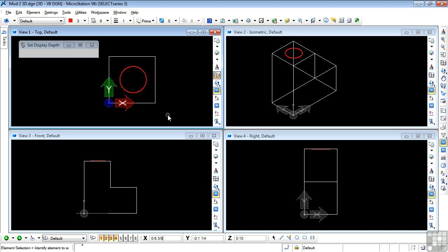And in fact, if you do set an active depth which is outside the active depth location, then the back clipping plane that you set becomes the location of the active depth, which may not be what you want. So you do have to be a little careful about that, and you have to know where the current active depth is before you place more clipping planes.